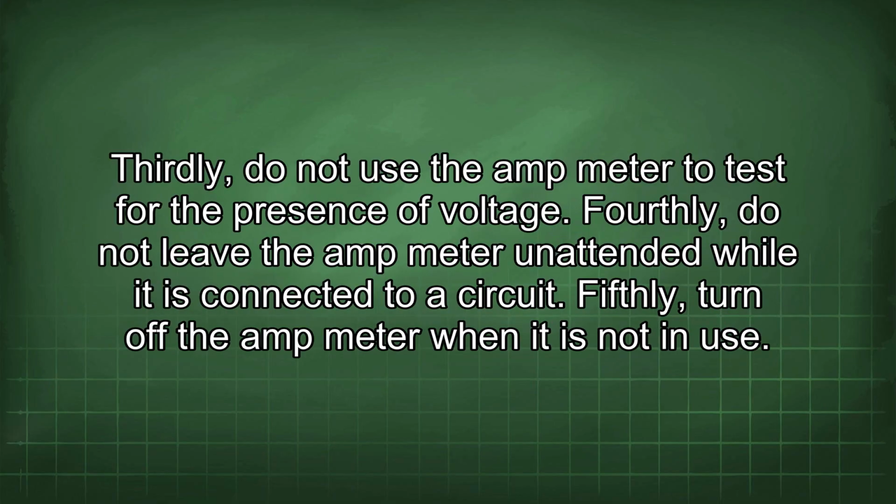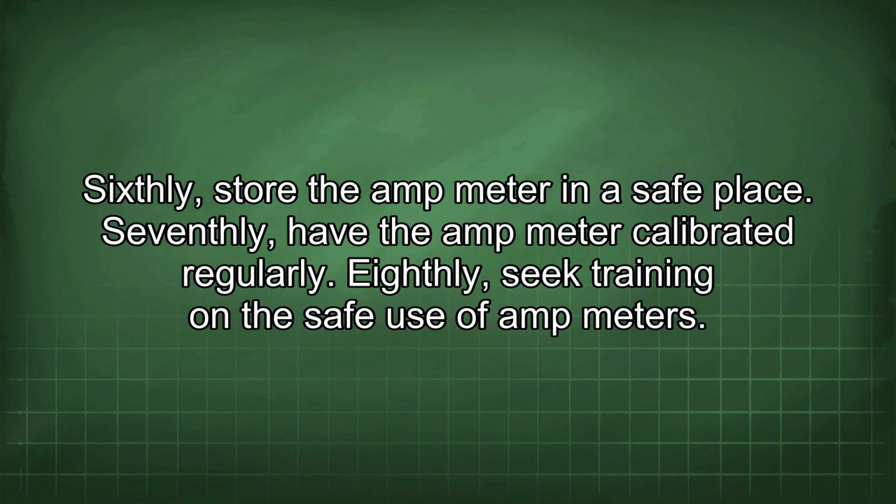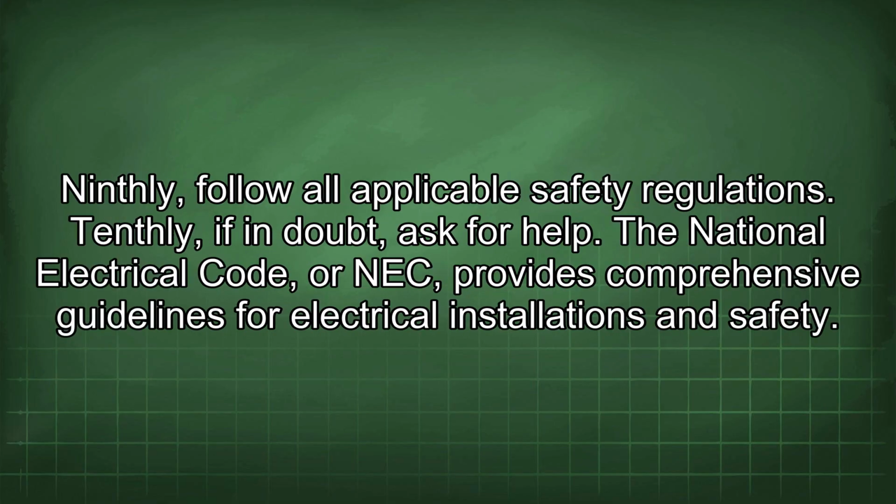Thirdly, do not use the amp meter to test for the presence of voltage. Fourthly, do not leave the amp meter unattended while it is connected to a circuit. Fifthly, turn off the amp meter when it is not in use. Sixthly, store the amp meter in a safe place. Seventhly, have the amp meter calibrated regularly. Eighthly, seek training on the safe use of amp meters. Ninthly, follow all applicable safety regulations. Tenthly, if in doubt, ask for help.